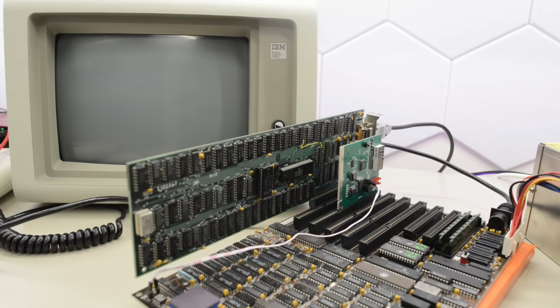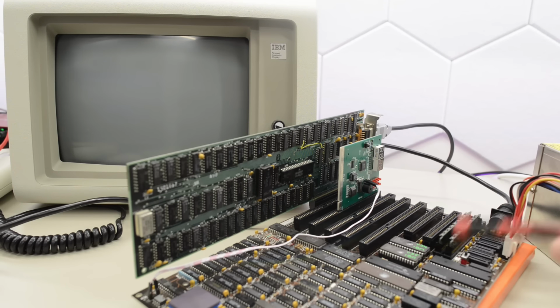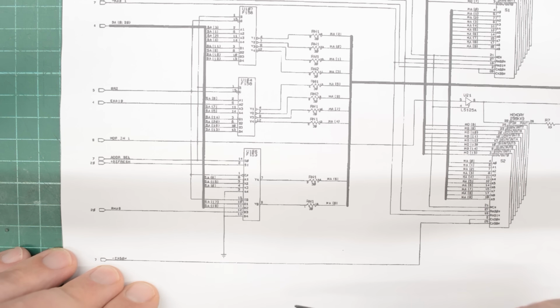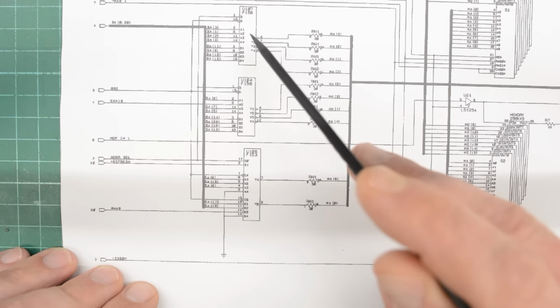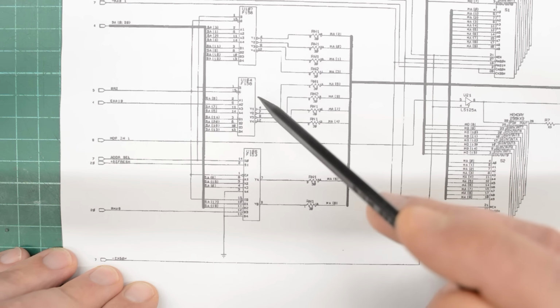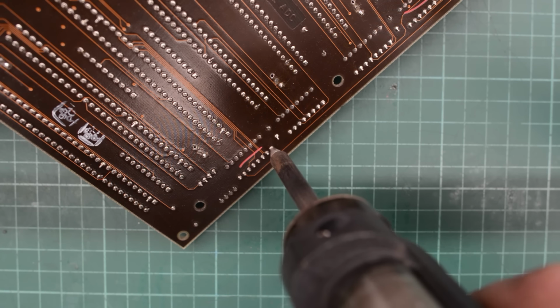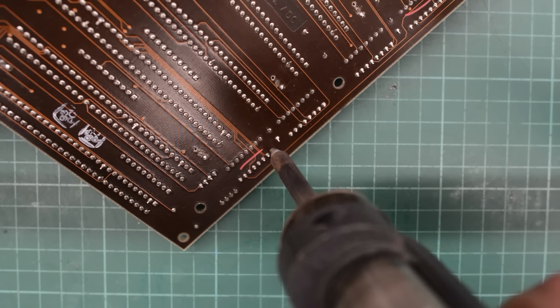So I decided to desolder a proper LS125 chip from a working system and install it on this board now. Let's see if this makes a difference. No difference whatsoever. So at least we have ruled out one more chip. Okay, our next two suspects are these two F158s, U107 and U104. This is a bit more guesswork than I would have liked, but I'm not sure what else I could check at the moment.